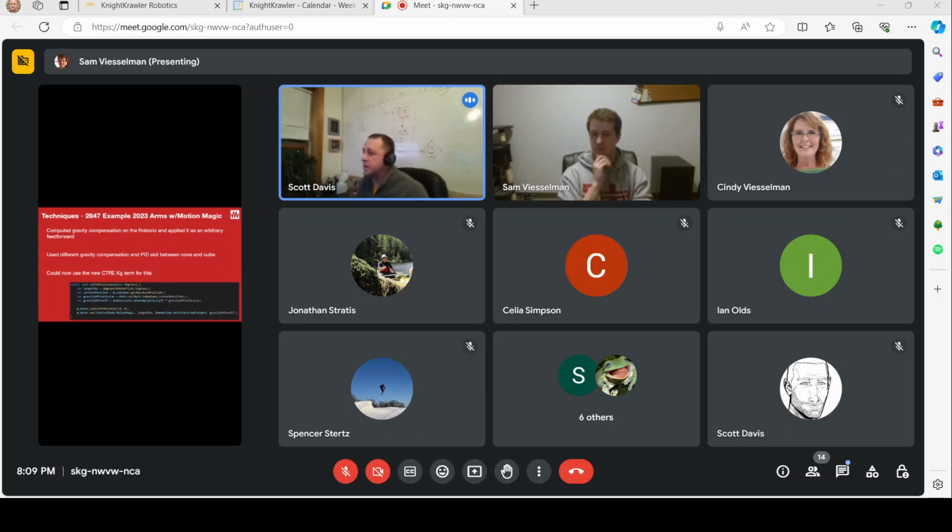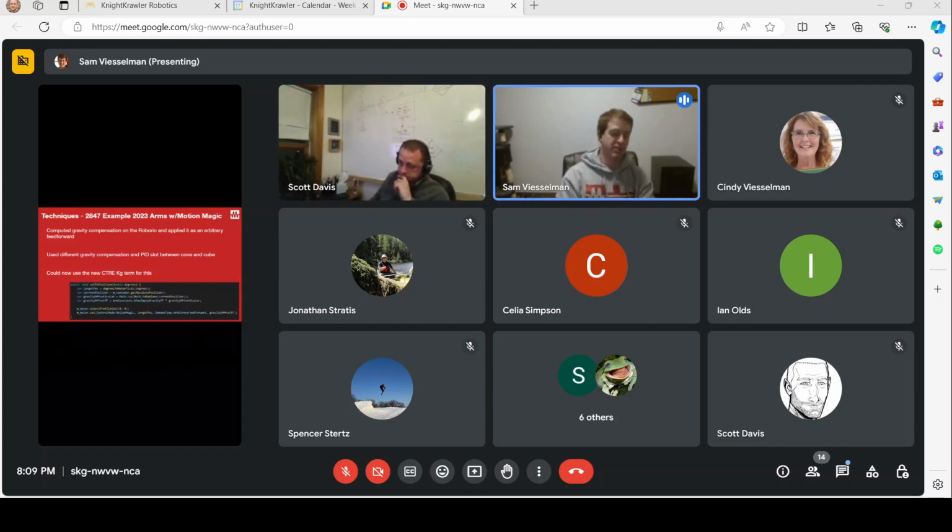All right, then I will send a message to my programmers tonight that we need to rewire that and have that run directly into the SparkMax and see if we can control it that way. It's good advice. And yeah, the big driver for that is that way you can run the control loop on the Max controller, which is going to do that at 1 millisecond instead of the 20 milliseconds on the Rio. You can get the KP way higher, which means it's just going to resist change even more. It's going to really lock in, and it should be faster.